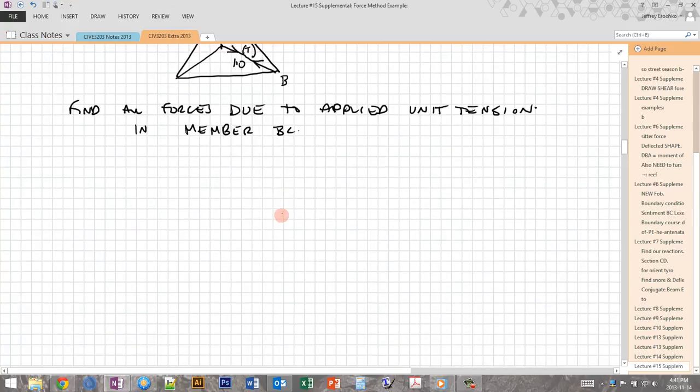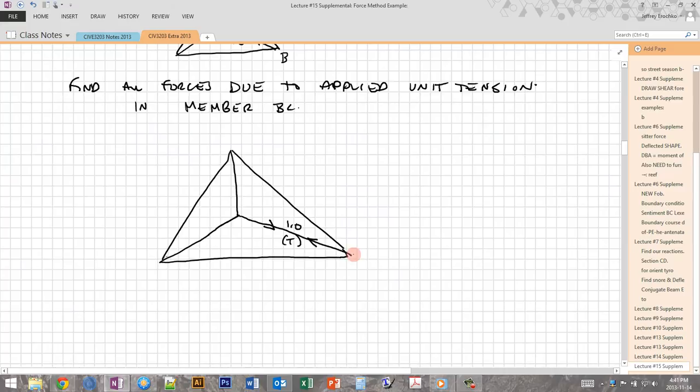So I'm going to redraw the truss and redo a truss analysis. I'm going to start with this. There are no external reaction loads because there are no external loads applied. So I'm just going to look at this in terms of the internal truss loads, C and D. And so now starting with this one, I can find this force here, which is negative 0.790. I won't go over the details of how to do this, and you can check out the truss example video in order to find out how to do this if you don't already know.